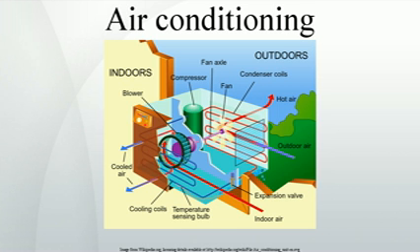The R12 was replaced with R134a, a refrigerant which has a lower ozone depletion potential. Old R12 systems can be retrofitted to R134a by a complete flush and filter dryer replacement to remove the mineral oil, which is not compatible with R134a.